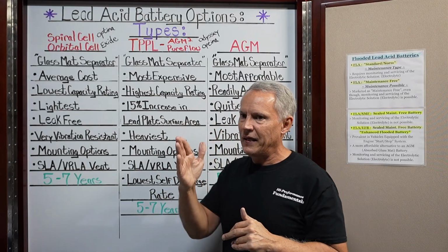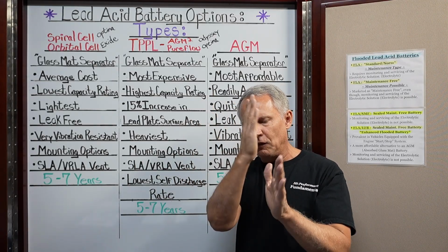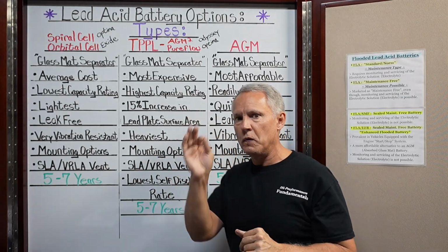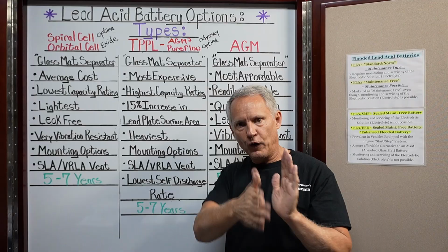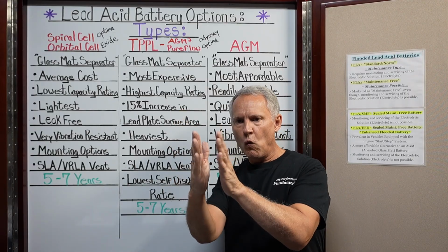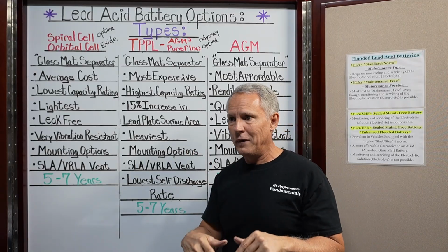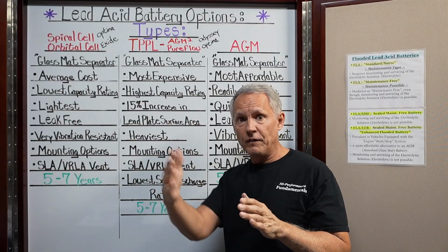So if we were to make each of the positive and negative plates throughout the battery thinner, of a higher quality material but thinner, we could put more plates in there, couldn't we? Instead of like 4 thick positive plates and 5 thick negative plates, if we use thin plates, we might could get 10 of one and 11 of the other.